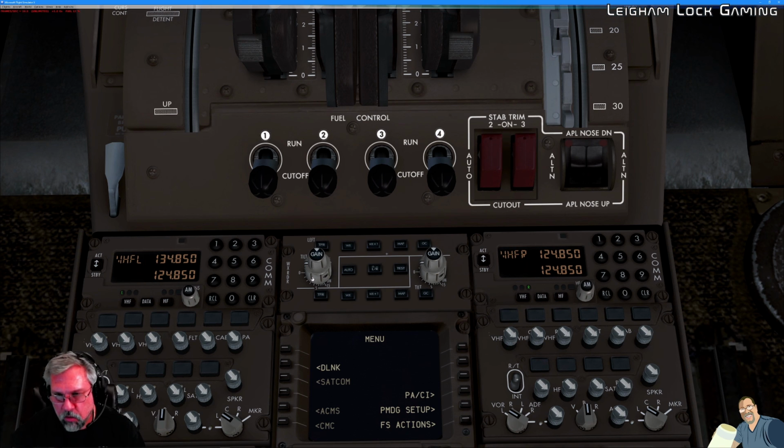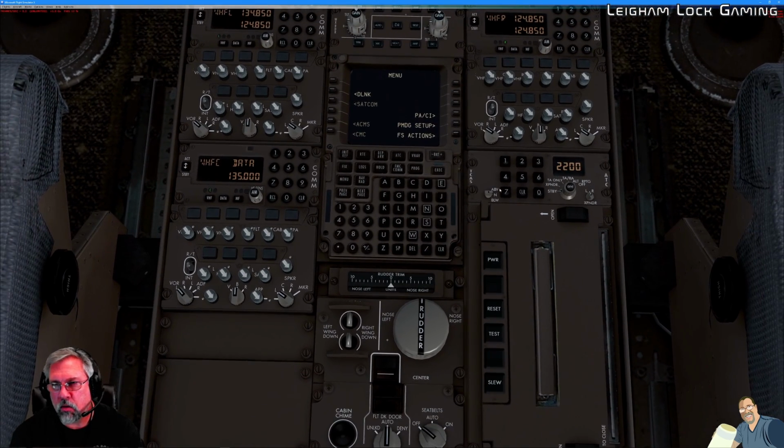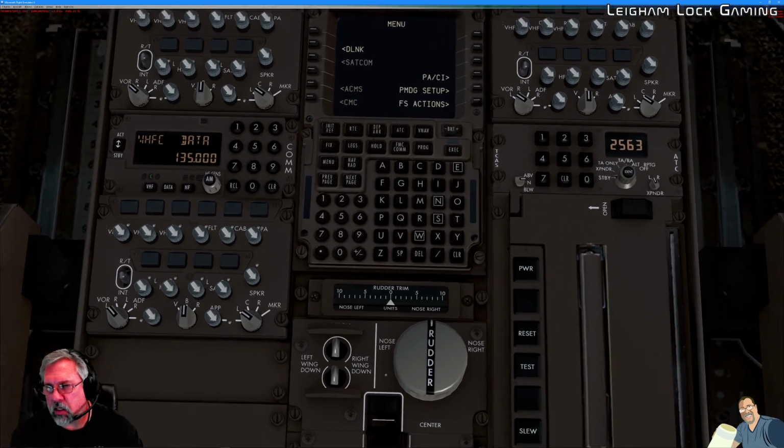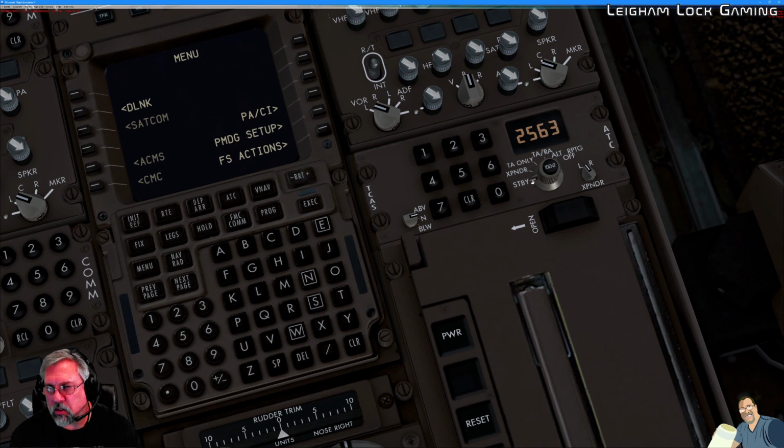And now we want to go to the transponder, so I'm going to back out here. Go ahead and put in a transponder code. Confirm that we are in standby, and we are. A little hard to see. I liked it when it highlighted before and it would tell you where it is, but you can see the little notch here in the button. So we are in standby.